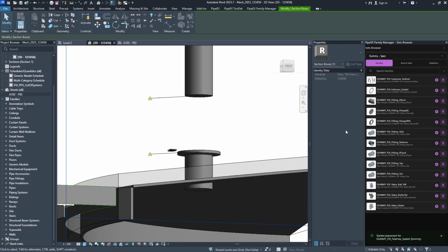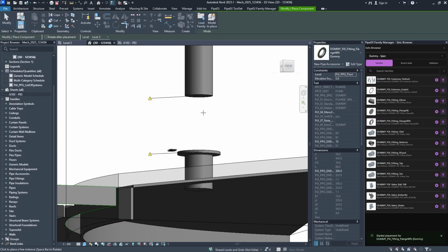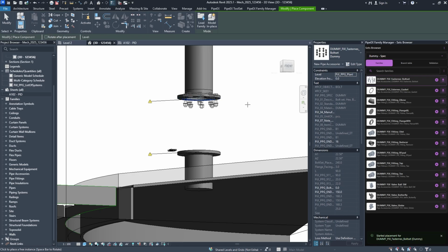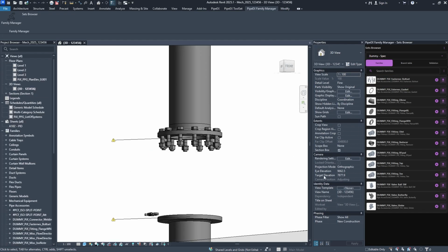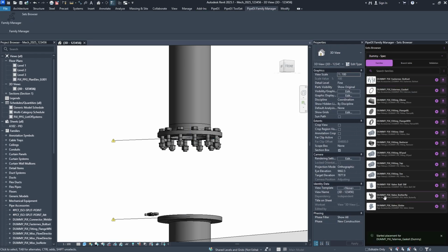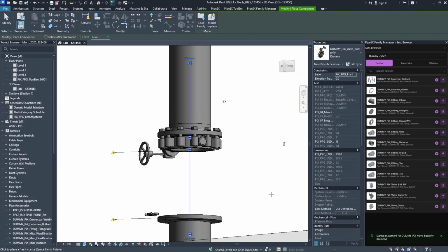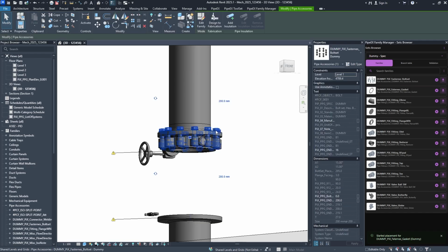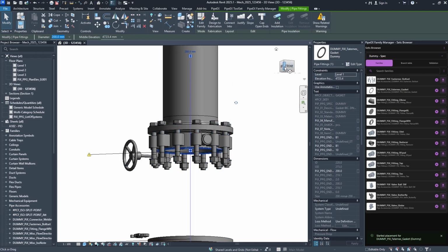We also are going to start from a weld neck flange, then bolt set. Now I need to add a gasket, then again it will be our butterfly valve and another gasket. Here I just need to change it to 160 and we can reconnect it.